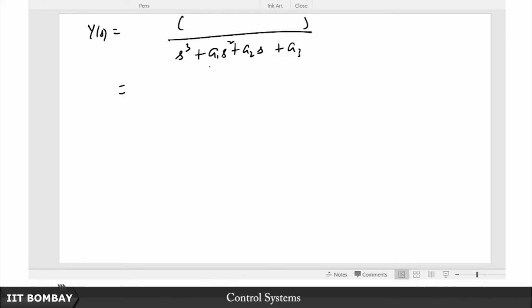So, this will contain, if there are real poles only, basically 3 terms like a1 by s minus p1 plus a2 over s minus p2 plus a3 over s minus p3. Even if they are complex, I do not care, all that I need to bother with is that the corresponding coefficient will also have to be complex then, as we have seen in the previous lecture. So, therefore, we at least know how to solve, using Laplace transforms, for the 0 input response of a system. And we have also seen the beautiful thing that this is always going to be strictly proper.